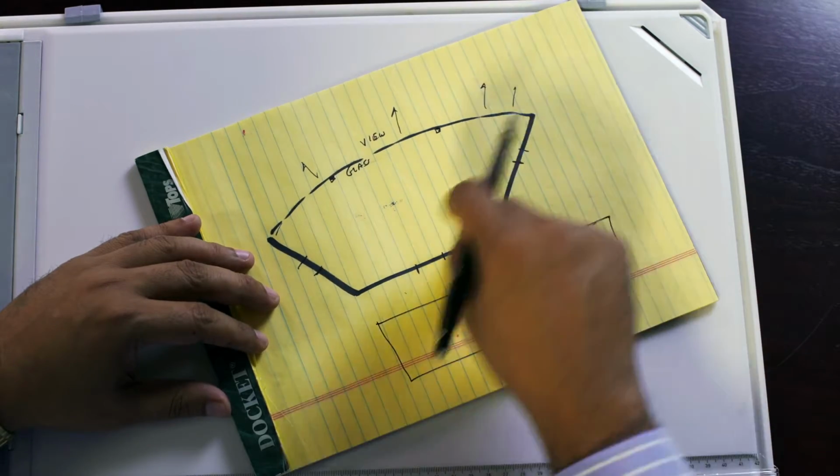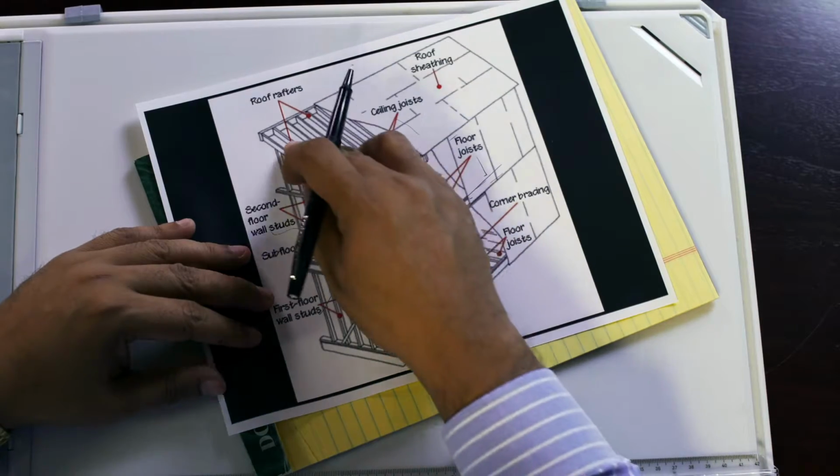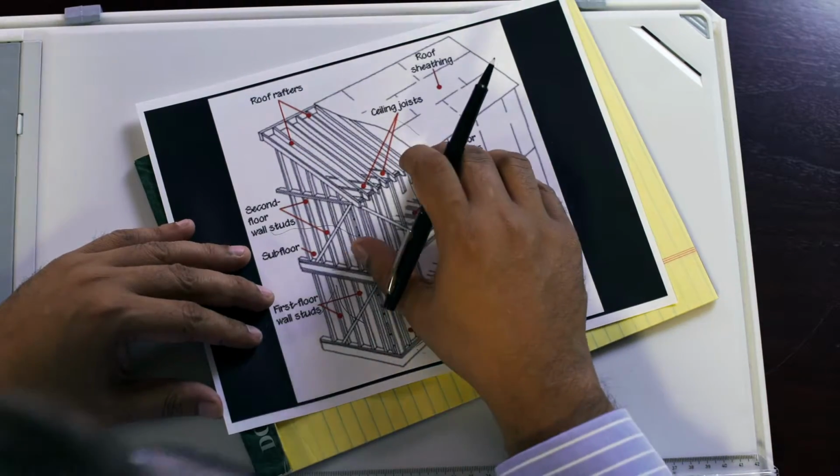We can make plans like this work, but you need to be aware that you have load path that has to transfer from floor joists to columns and get down to the foundation. Always remember, continuous load path, very important. Probably the single most area where architects and engineers have disruption, because engineers like to have symmetry, architects want to have anti-symmetry or creativity.